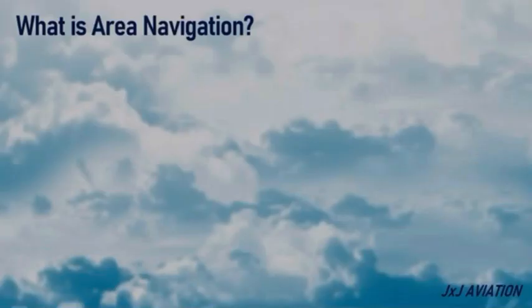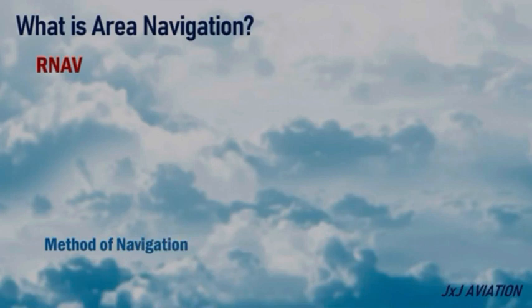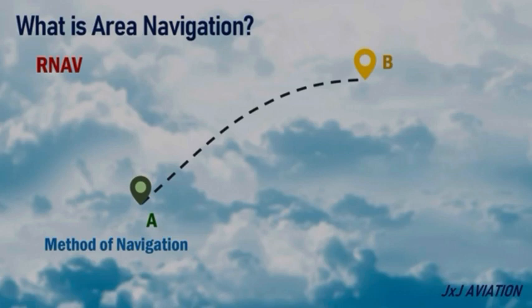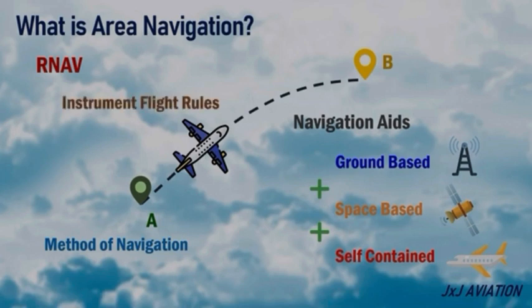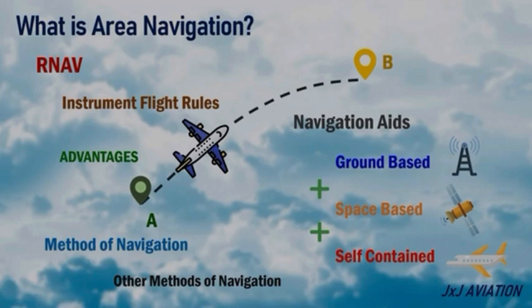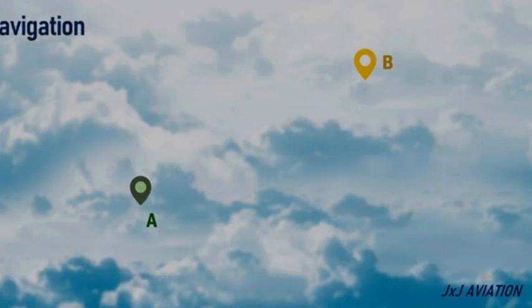For example, if we fly a designated route, in between we have a VOR, so we need to follow, for example, an inbound radial to the VOR, then fly over the VOR, and then follow an outbound radial. So this type of navigation is a sensor-based navigation, because we are tied to a sensor, which is the VOR located on the ground. So we need the signal from the VOR, and using the signal we can fly inbound and then outbound to a designated point. But the main benefit of the PBN is that such operation is totally ignored.